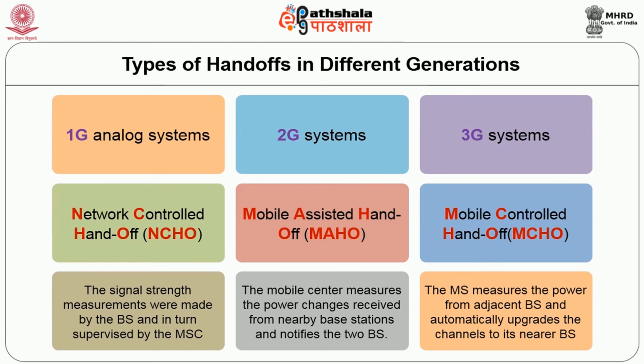The base station monitors the signal strength of the voice channel to determine the relative position of the subscriber. The MSC monitors the signal strength of the users in neighboring cells that appear to be in need of handover. So handover is maintained by the network, hence the name network controlled handover.